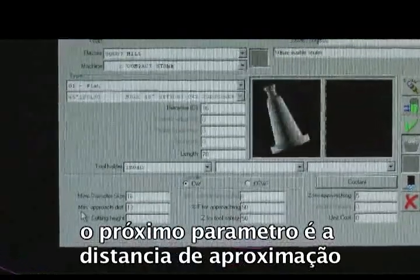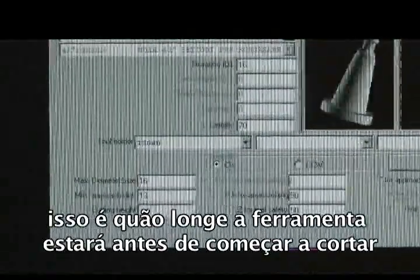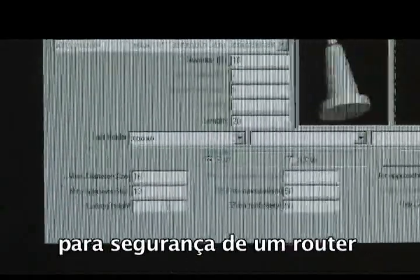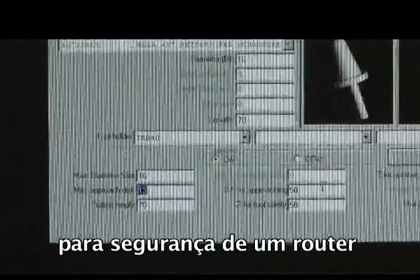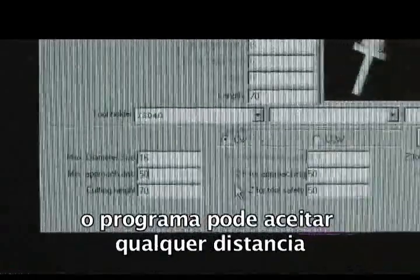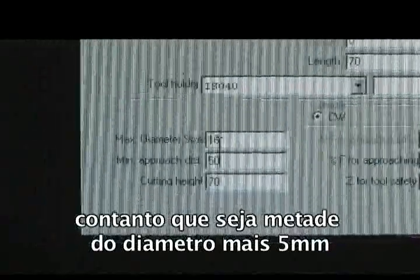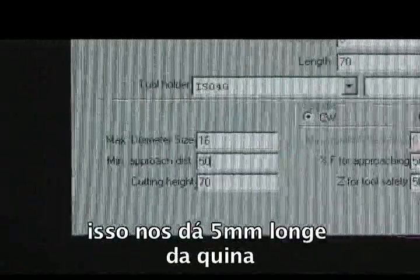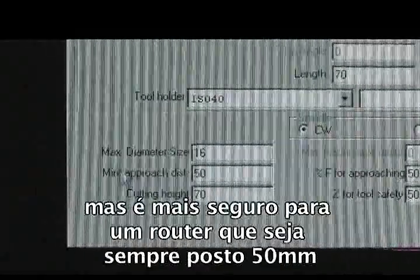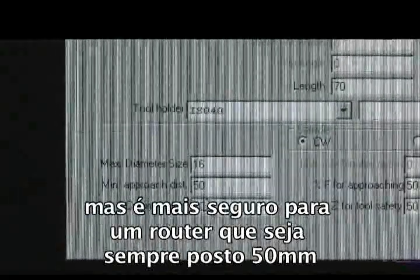Our next parameter is minimum approach distance. This is how far away from the edge of the material the tool will start before it cuts. As a safety setting for a router, we'll put it to 50mm. The software can accept any distance so long as it's half the maximum diameter plus 5mm. So that gives it a 5mm distance away from the edge. But it's safer for a router that it's always set to 50.